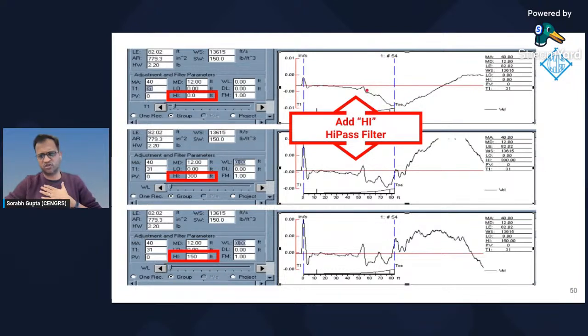But are we interested in the soil resistance? No. Why? Because the purpose of the PIT is to only understand the structural integrity of the pile shaft concrete. So we need to remove the effect of the soil, and we do that by using something known as a high pass filter. In the top graph, the one which we processed earlier, the same pile, same signal, we got some drift because the high pass was 0.